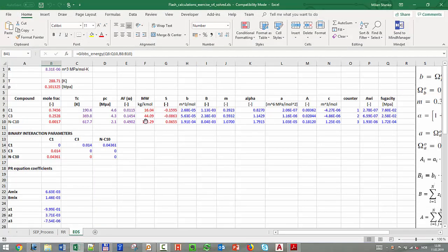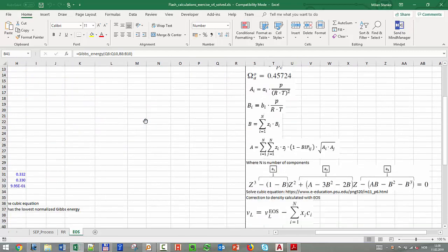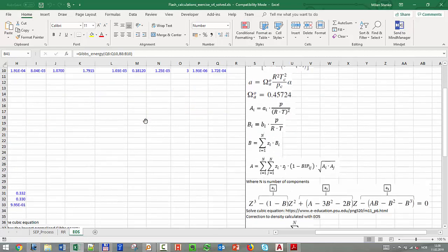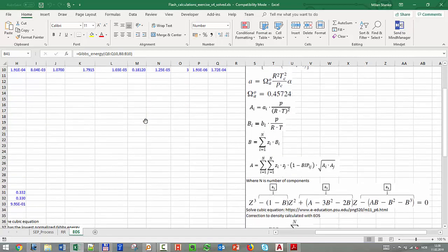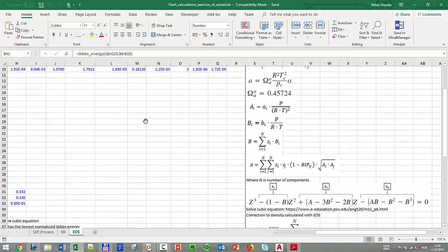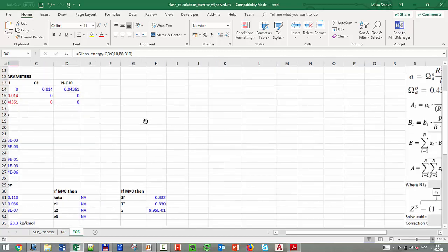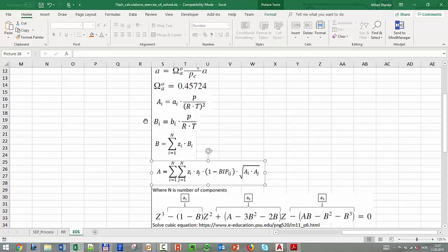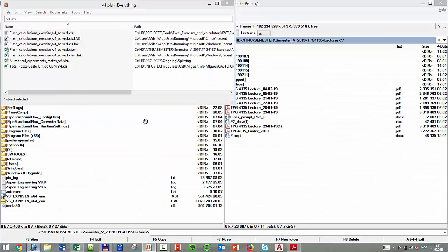We have here our EOS part, and if you remember, these BIPs are used to calculate this A of the equation, the A that goes in front of this term. You needed to have these BIPs, which we call binary interaction parameters. If you use them by default, maybe the predictability is not very good. So if you adjust them slightly, then you get much better precision, much better accuracy. So that's typically what is done in the equation of state to try to improve.